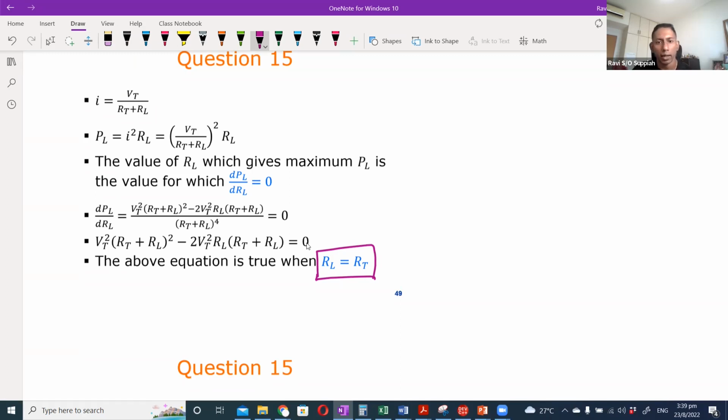Okay, so again, this is quite important, because when your load resistance does not match the Thevenin's resistance, you may still get some output, but it may not be the optimal output, because the maximum power is not transferred over.